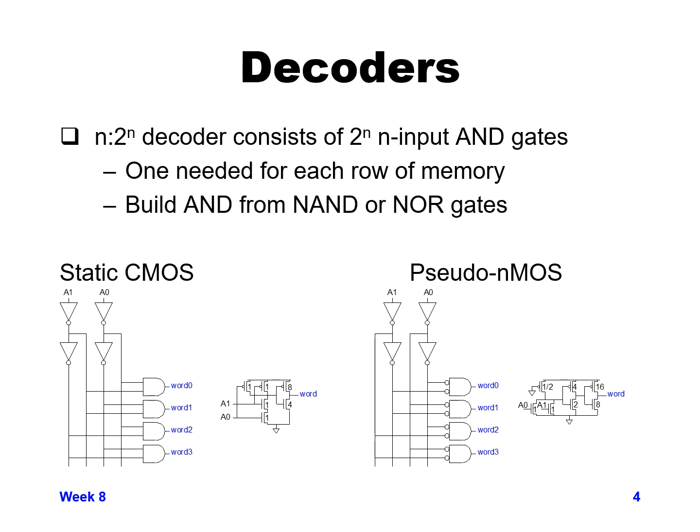Now that we've talked about the basics of the bit cell, reading and writing from the bit cell, and how it's constructed into an array and columns, we need to talk about driving our word lines. In order to drive our word lines, we need decoders. For whatever our word size is, we need n number of bits to come in in order to drive 2 to the n number of word lines.